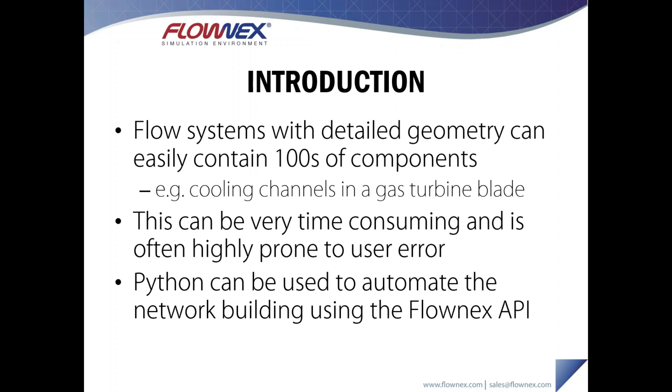So what is a convenient thing to do is instead to represent these complex networks in a data file. This data file could be extracted from some CAD geometry, or it could simply just be an Excel file where you describe the main features and say a constant offset between components. You could then use a code like Python to read in this data file, interpret it, and then generate components automatically using loops to minimize the time that you spend coding, and then at the same time incrementing all the inputs correctly so that the inputs for the components are specified exactly as you intended.